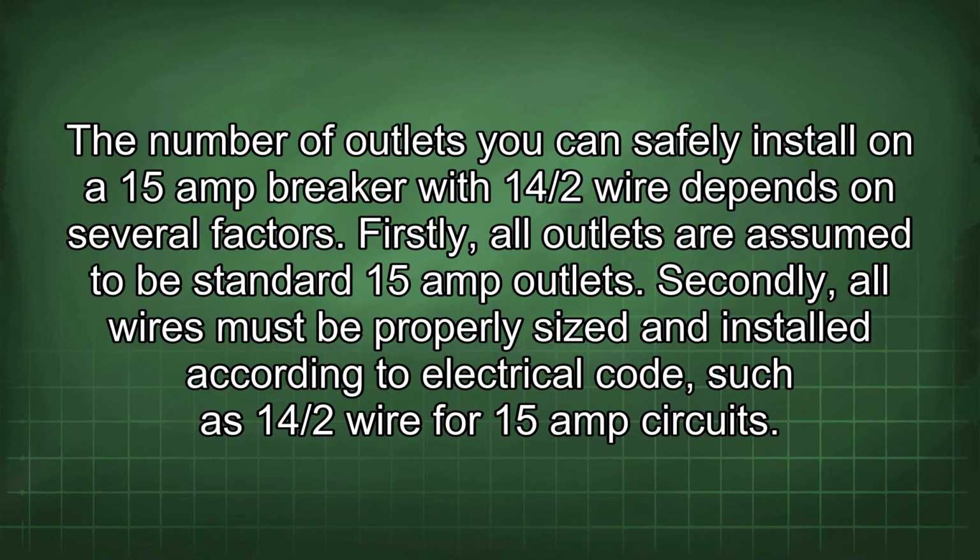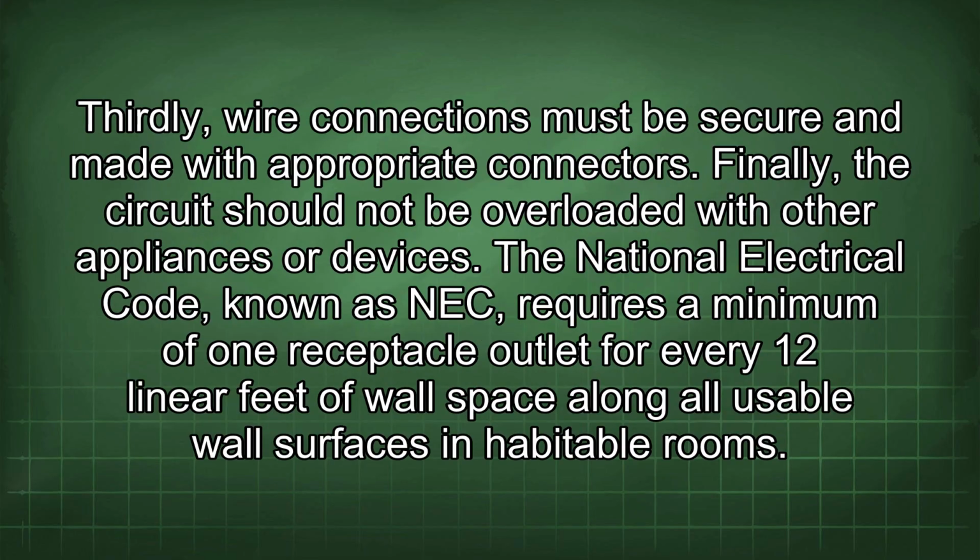The number of outlets you can safely install on a 15-amp breaker with 14/2 wire depends on several factors. Firstly, all outlets are assumed to be standard 15-amp outlets. Secondly, all wires must be properly sized and installed according to electrical code, such as 14/2 wire for 15-amp circuits. Thirdly, wire connections must be secure and made with appropriate connectors. Finally, the circuit should not be overloaded with other appliances or devices.